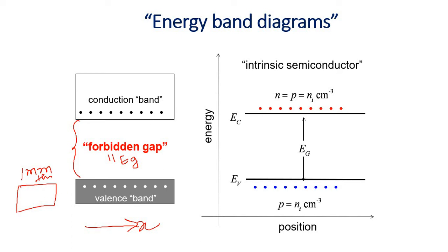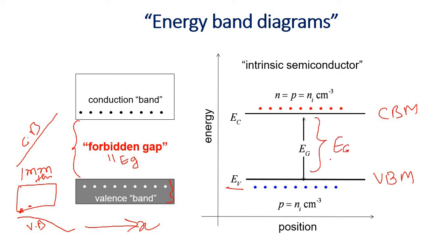So how are these bands moving? Suppose this band can go down, like this, the conduction band. Okay, maybe the valence band, maybe this. So with position it may be different if they are moving. Okay, so these are constant. We will discuss later what will happen, but right now it is important to take it as a constant. So nobody is going to draw the bands' upper limit or lower limit. People will draw the valence band maxima. This is called EV, and the conduction band minima people will say EC. The difference between these two is called EG, the band gap. Okay.